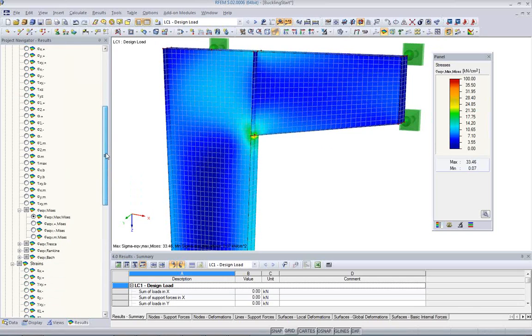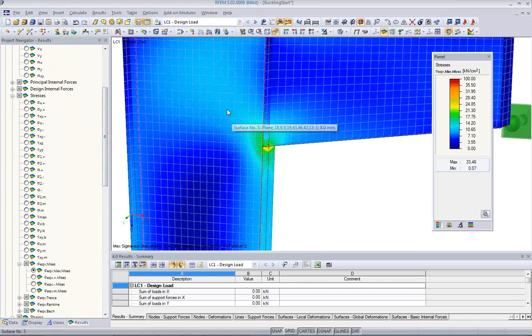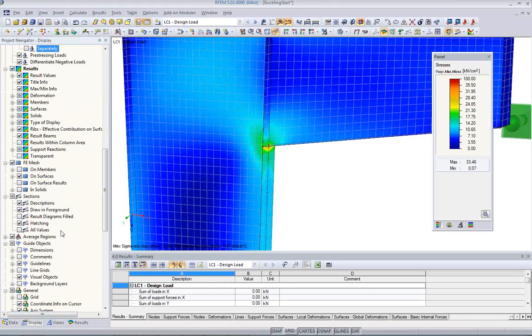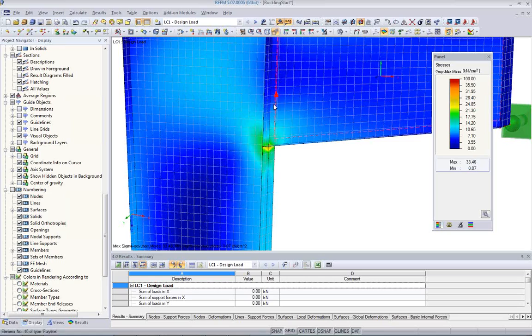First of all, we change the stiffness for each mesh cell. And therefore it is not a good idea to smooth the results, which is what we do by default over all surfaces. RFEM has some specialty in how it displays results. Generally, you get rough results and you want to smooth them over one surface.